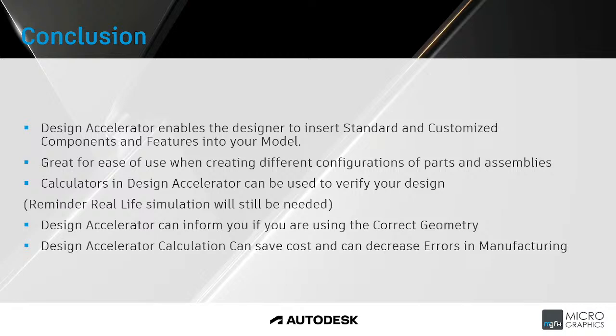So this is for me one of the most important parts of Design Accelerator. The Design Accelerator calculation can actually save cost and can decrease errors in manufacturing. When you run your calculations, it actually shows you, for instance, let's take the shaft. Your one diameter is too small, and you run your simulation and you see with your calculation you need to increase.